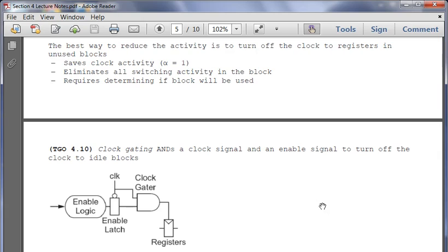So clock gating, to tie in here: you have a clock, and you have this enable logic. The enable logic determines which one. From architecture, you have certain control signals that go to the ALU out, and they're going to memory, right? You have to add another enable logic that knows which ones we want to use. In section 1, towards the end, I showed what's known as a multi-cycle MIPS architecture, which doesn't quite have the performance benefits of, say, the pipeline data path.